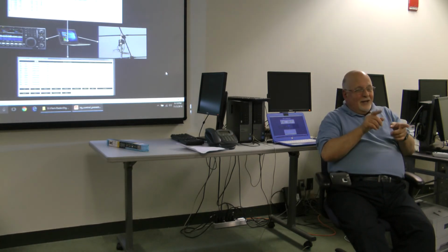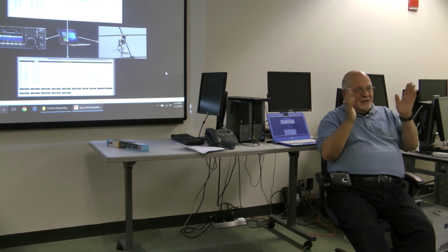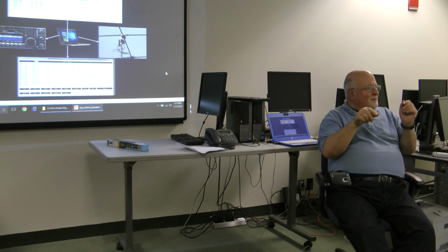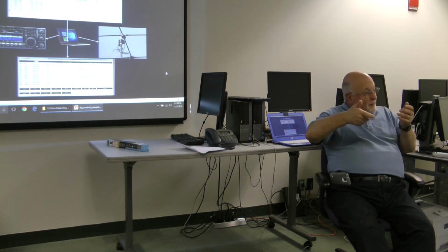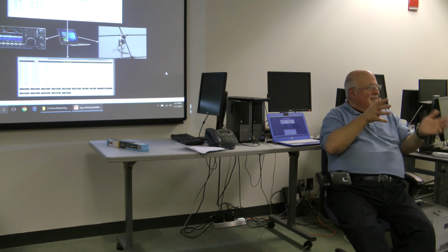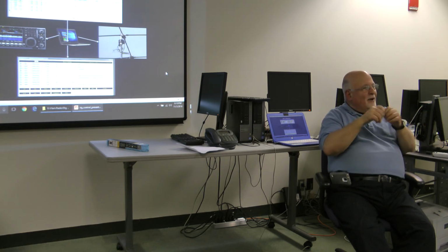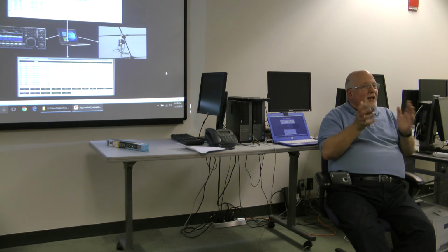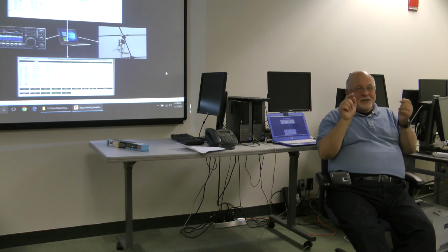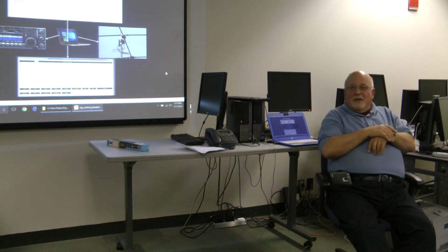I got to go to the frequency, press the button that sets the receive and transmit frequencies the same. Then I go over to the B VFO, set that up 5, switch back to the A VFO so that I'm listening on the A, and then press the button to tell it to do split operations. By that time, he's done 20 other QSOs and he's off the air. Now it's literally one click, the split is set, and away you go.